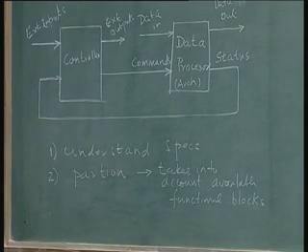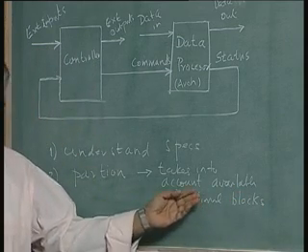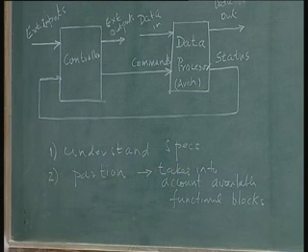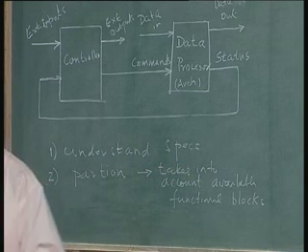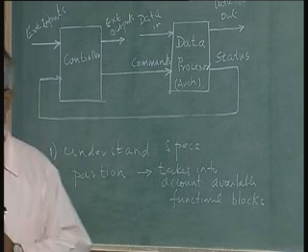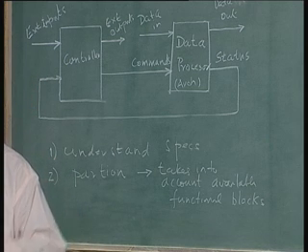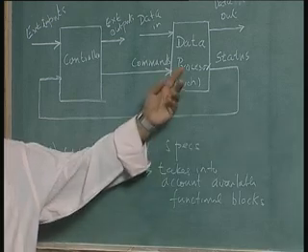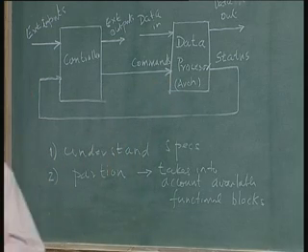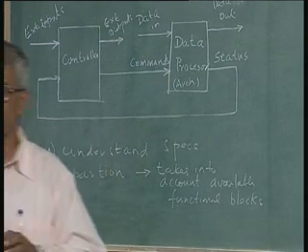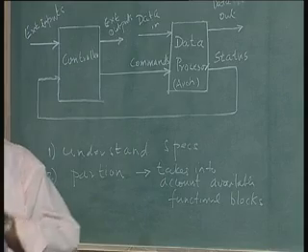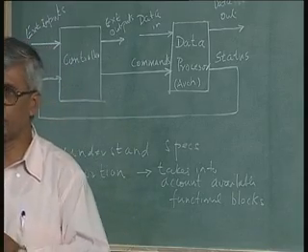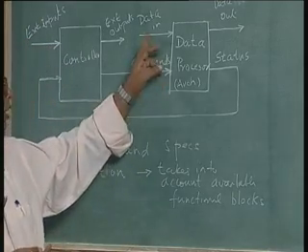And once you have these available functional blocks, then you also know what the input output specifications of each of these functional blocks are. In addition to the data processing ability, take an example of a register. You want to use a register as one of the functional blocks of the architecture. A register is meant to store data. So, there should be data in, and if you want to read the data from the register, data out. So, this corresponds to data in, data out.